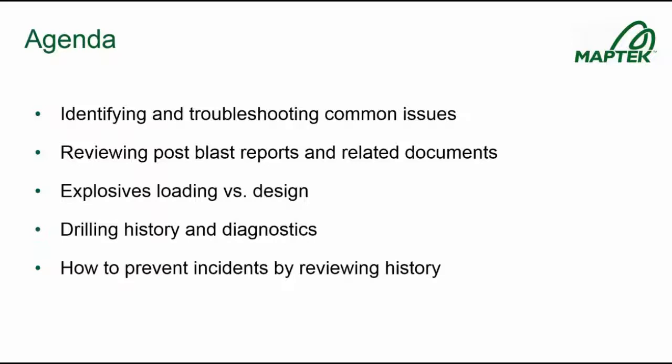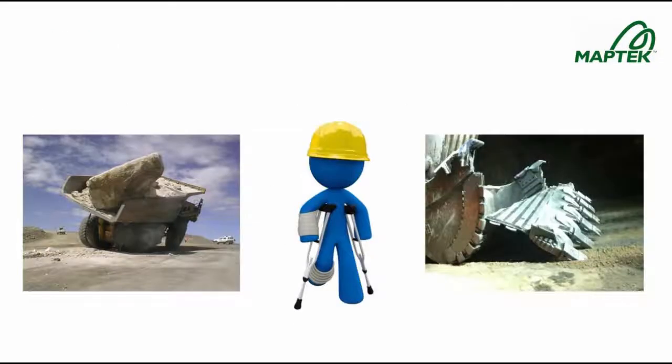Now, when I talk about blasting incidents, the main factors we usually come across are if you had some sort of oversize where you had to do secondary blasting, and that's usually just a budget time crunch, so you're falling behind on production. There's also, of course, personal injuries, which we always want to avoid. If they do occur, there's pretty much a guarantee that there's going to have to be some sort of report or investigation. And the same with typical equipment damage. And then the unmentionable is, of course, a misfire. Misfires usually always require an investigation.